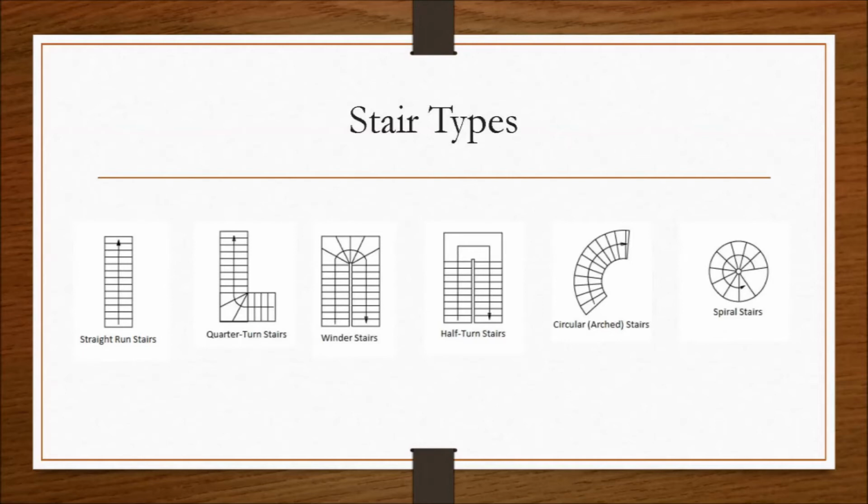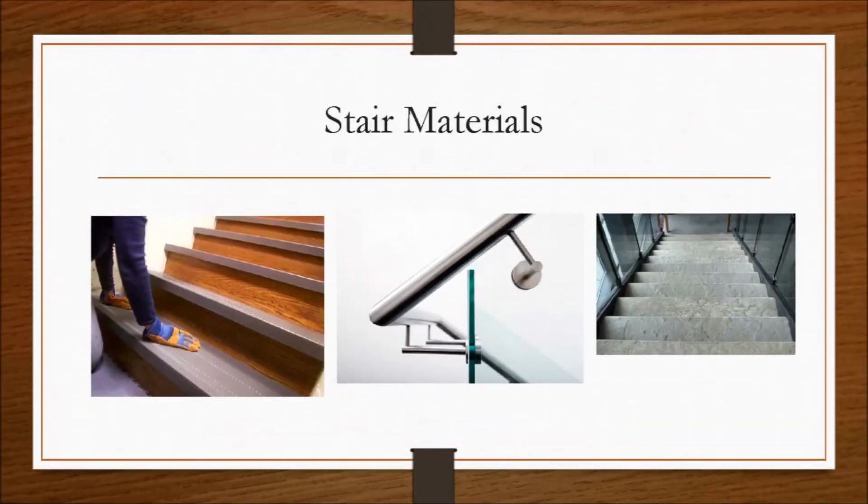Steel channels may be supported by beams, rest on masonry walls, or be hung on threaded rods from the floor structure above. The ends and underside of steel stairs may be left exposed to view or finished with gypsum board or metal lath and plaster. Metal stairs may be noisy when in use.